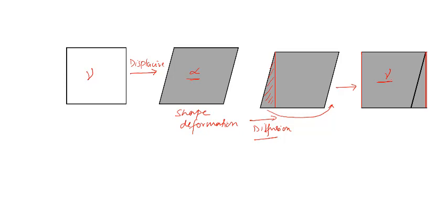If diffusion is not allowed, then this shape deformation is going to remain and give rise to some kind of strain in the parent lattice, because the parent lattice would restrict this shape change, right? What is the meaning of this? The meaning of this is, if the diffusion is not allowed, then I would have a shape deformation which cannot be eliminated, right? So that is what is going to happen in case of Martensite transformation.